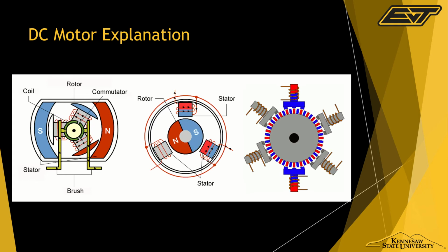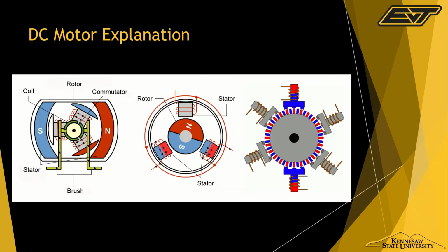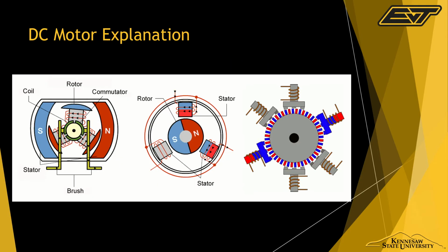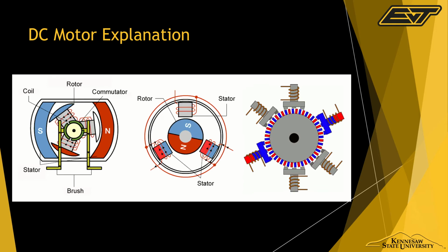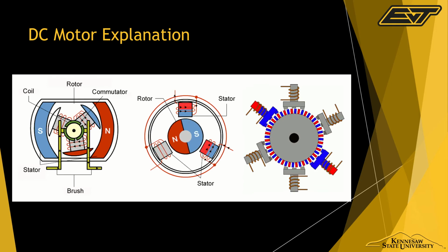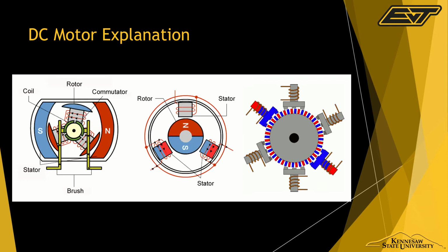The bad thing about DC motors is that they have very low efficiency. Even a high efficiency DC motor, you'll see efficiencies around 88%. The reason is that there's a lot of energy loss around the brushes. You don't ever have perfect contact, even though there are springs there. And there's arcing.